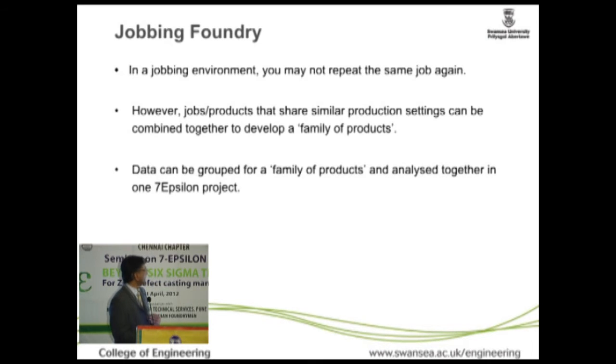You need to quantify these product characteristics so that the software or data visualization tool will recognize the variation within the family. For example, this particular one has a sharp change between section thickness, or the variation in section thickness, variation in the parting line, the cores, undercuts.